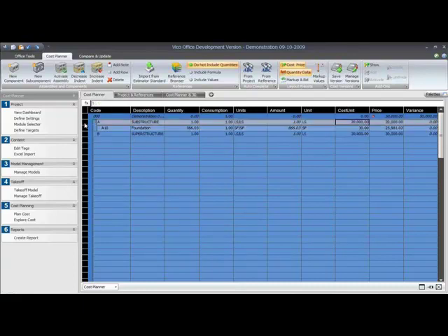And again, we're going to activate that component in the substructure. So at this moment, this value doesn't do anything. It is only added to the project's total cost as soon as I activate the assembly. So I select the substructure level, click the Activate Assembly, and at that moment, the 20,000 that I had earlier is replaced with the new value of 25,000.